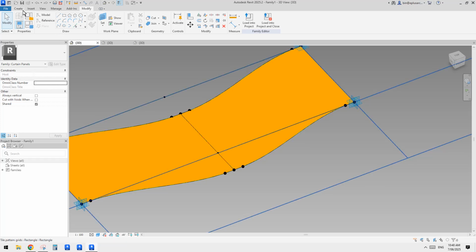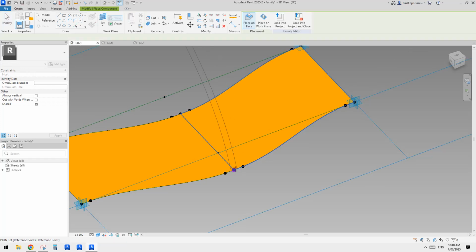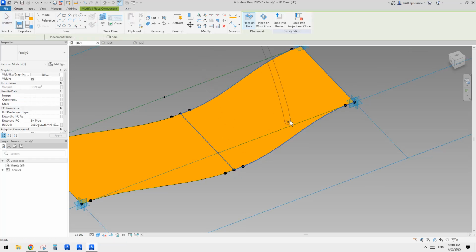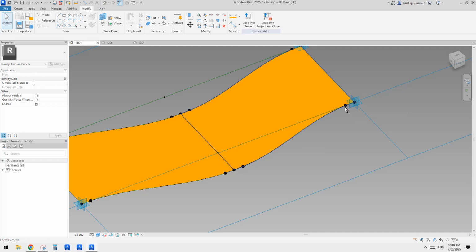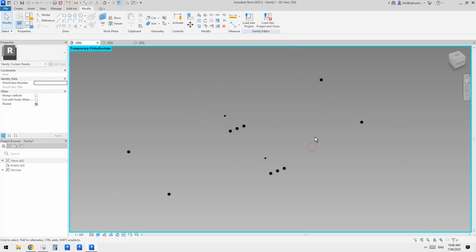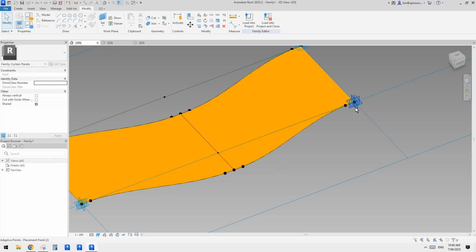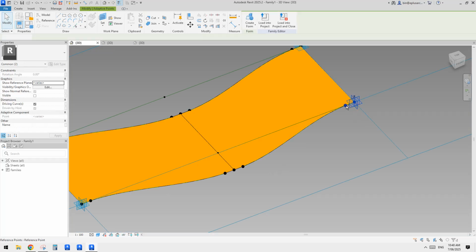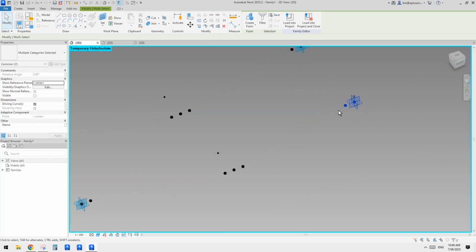Okay, so let's create components. This time place onto the point. And actually I'll just type one of the points, type IC. Yeah, that's better, so we won't accidentally pick the lines. That's only one point. Where's the other one? That's the adaptive point. So Control Z. I'll select this point and Control select this one. Type IC. Okay, now we have all the points we need.